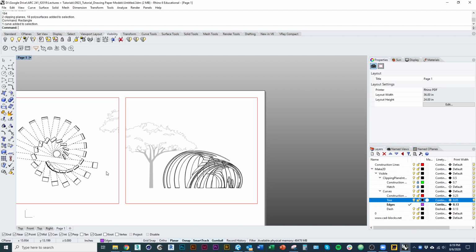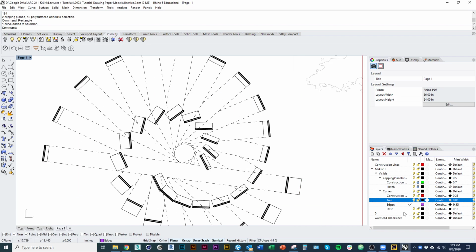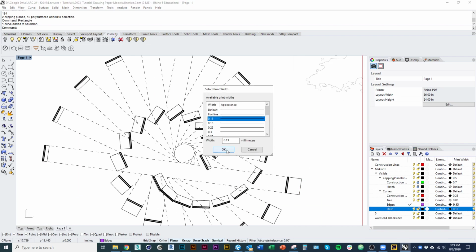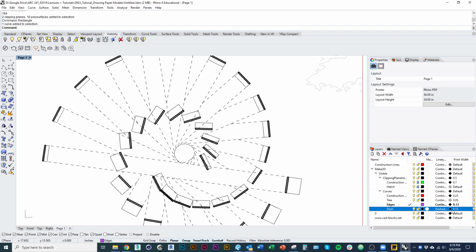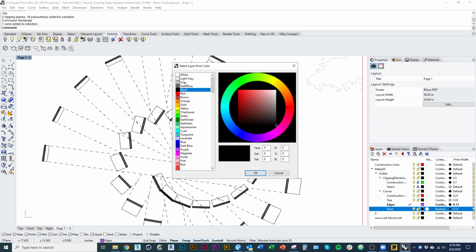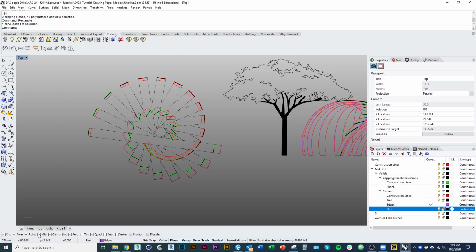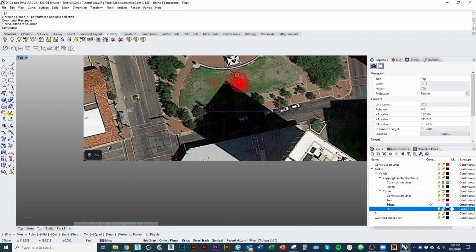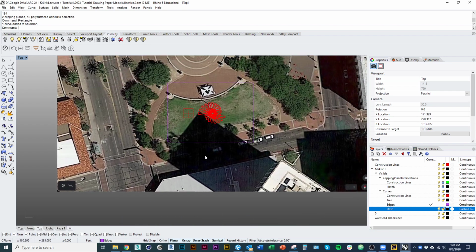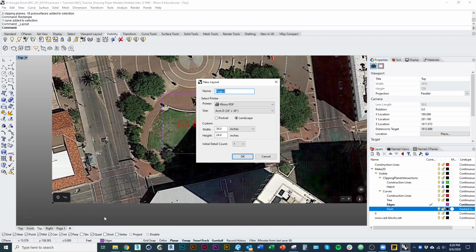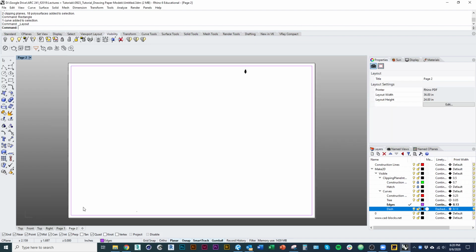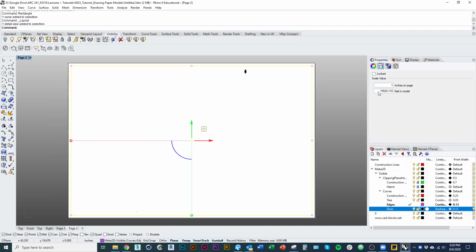This is showing the object cut through, more zoomed in to show the actual space within. But we also want to show a site plan, which would be like the roof plan of our pavilion. And in that plan, we'd be a little more zoomed out. So let me make a new layout really quick to explore how big that would be. And I think that it would make sense to do that at a 1/16 of an inch, which is 0.0625.